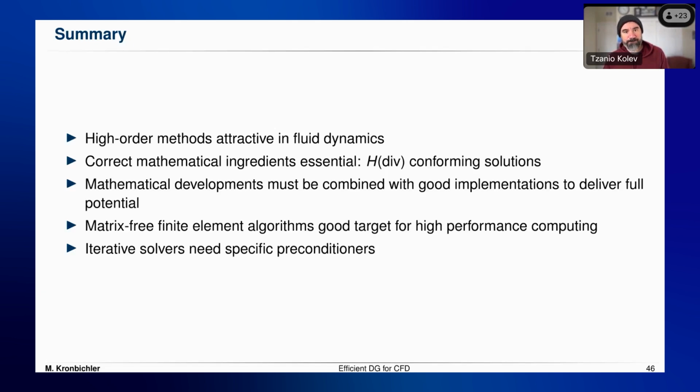Martin, I have a question about your projection method. My understanding is that this is a Chorin-type projection method in which you solve the Poisson equation for the pressure rather than for a pressure correction. And my question is, the splitting error of this method is probably first order in time. Does this time error pollute the accuracy of your high order finite element space discretization?